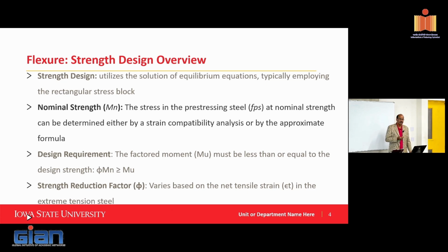When you use pre-stressing, obviously, if you haven't taken a pre-stress class, make sure you take the class. You will get that knowledge about how you do the pre-stressing. The pre-stressing steel has pretty high forces, and you have to account for that in the design calculation as well. You can do proper calculation using strain compatibility, because it does get challenging, and the code also provides some approximate values. Some of the numbers are recently disputed, but I assume the code will update those numbers as well.